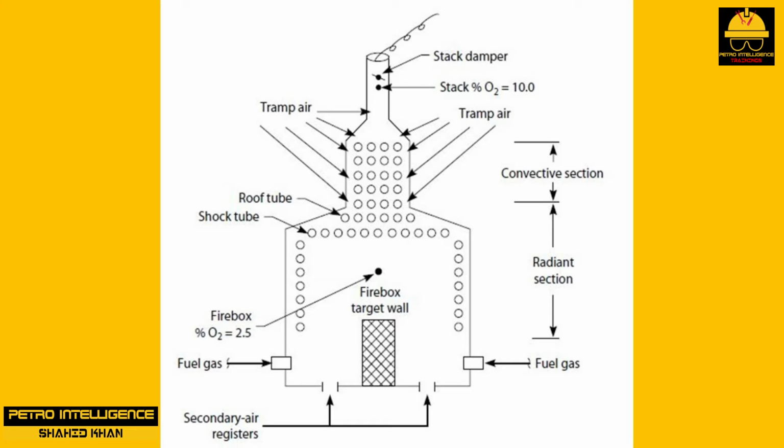If the combustion airflow is being adjusted on the basis of the oxygen content of the stack or convective section gases, that is, from readings taken on an oxygen analyzer with a probe located in the stack or convective section, there may be afterburn or secondary ignition in the convective section. The fire is supposed to be contained within the firebox, and not in the convective section.